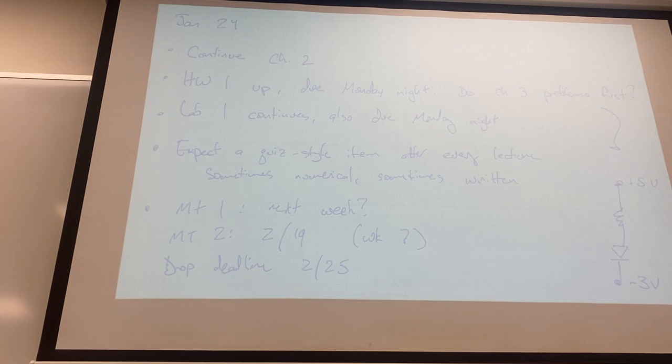The problems are sometimes 0.7, sometimes 0.6 or something else, just to keep you from getting too comfortable with that magic number and to know that it can change a little bit from situation to situation, mostly depending on how much current you're flowing through. And then they have a slightly more advanced model where you include a resistor, and we might talk a little bit more about that later on, but you basically try to model the slope of the real diode equation and say that's kind of the resistance in this local neighborhood. So we can think of it as even having a resistor and an ideal voltage source. Don't worry about that one on the homework, but just to give you kind of a preview.